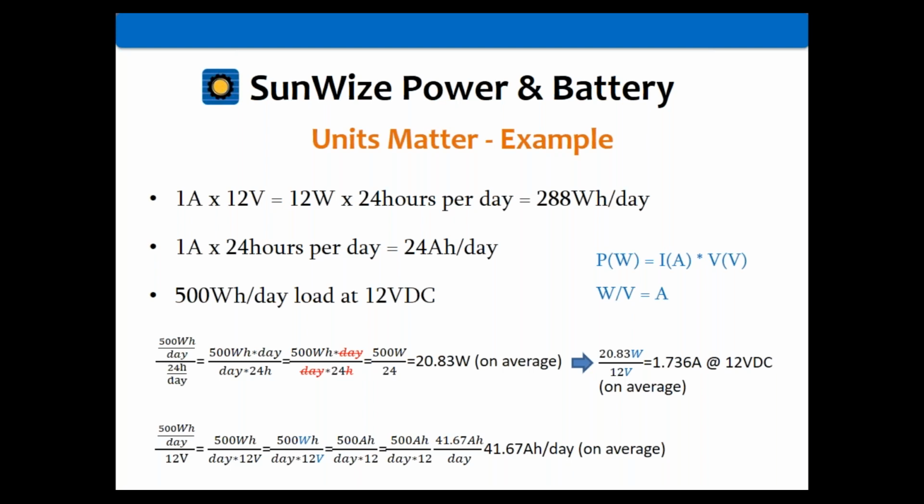Let's say you might want a 5-day autonomy for your solar power system. Well, you just take your 41.67, multiply it by 5 days, and that tells you how big your battery needs to be. So you can see how these units work together, and they help you to size your system. And again, we'll get into that in more detail next month, when we talk about basic system sizing. But again, you can see how these things are important in the solar industry, and how these things build upon themselves, and how they work together to help you in designing and sizing and specifying your solar system.